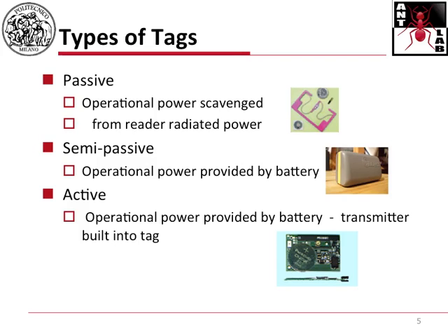If you open up this box, half or three quarters of the box is composed of a battery, and the remaining quarter is a semi-passive RFID tag, which is excited, triggered, when you get close to the toll booth, by a signal received from the toll booth. Then it uses the local battery to send some kind of signal to the toll booth machinery. Okay? Clear?